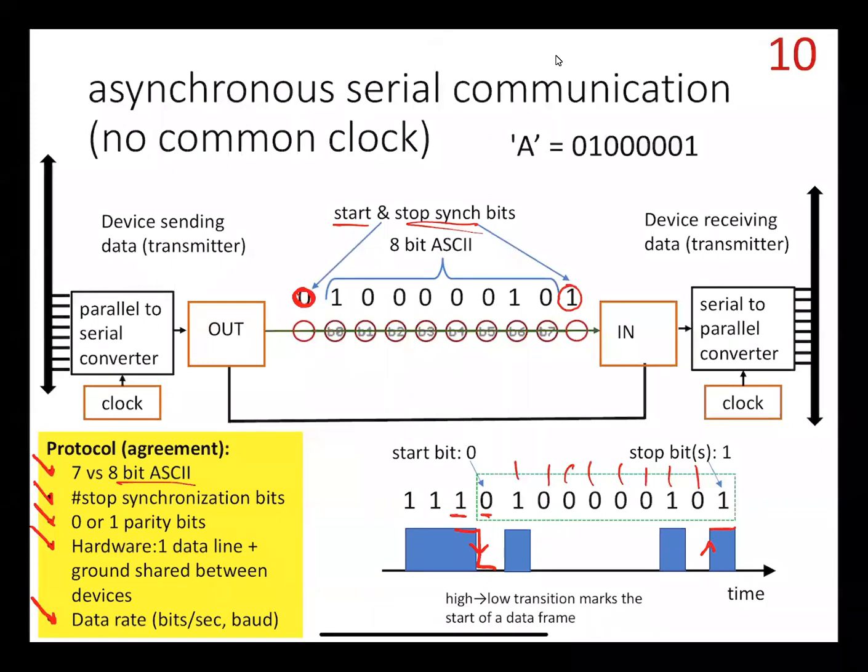Okay, so what else is going on in the hardware here? We are dealing with serial data transfer. So data inside the transmitter lives in memory registers that are 8 bits wide. And so what we would have coming off of our data bus would be all 8 lines coming off of our data bus.